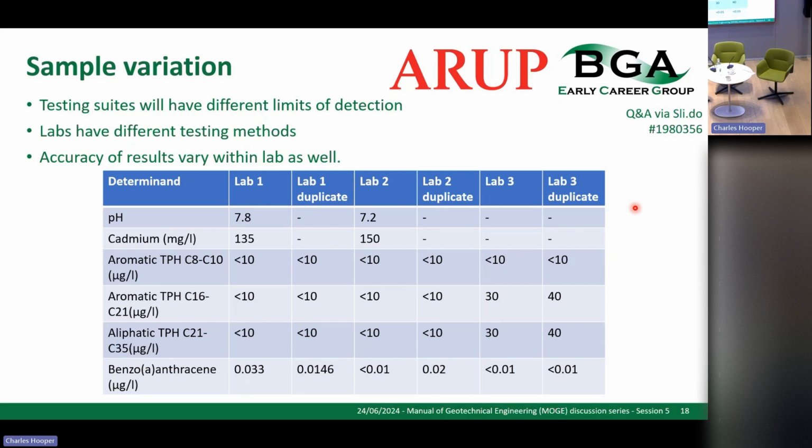So when you're taking your samples, you need to really think about how many you need to get an accurate number that you can rely upon. In this instance, they're still very low concentrations, but it was a really interesting experience. We hadn't appreciated how much variance there would be between labs on the exact same water sample, taken at the exact same time, with the exact same methods.